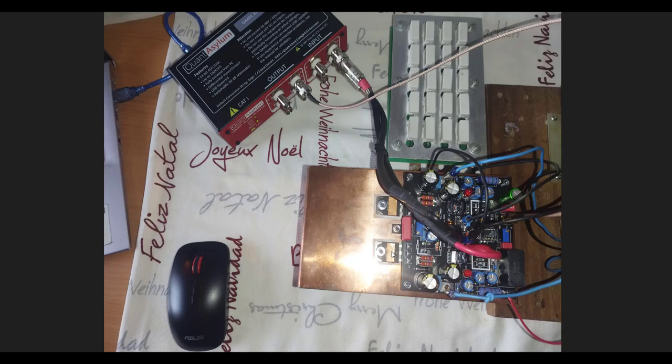let's say. But let's increase the open loop gain. We increase it, but after increasing, sometimes we end up in an instability situation. So the tip that I will pass today is to increase the open loop gain of the amplifier, and when we start to see some instability, we can do a small tune in the compensation to win some phase margin and some stability.